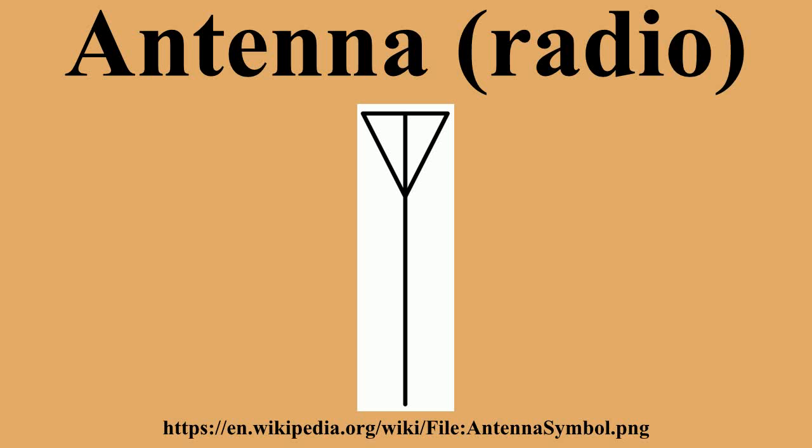Since monopole antennas rely on a conductive ground, a so-called grounding structure may be employed to provide a better ground contact to the Earth, which itself acts as a ground plane to perform that function regardless of an actual contact with the Earth. Antennas more complex than the dipole or vertical designs are usually intended to increase the directivity and consequently the gain of the antenna. This can be accomplished in many different ways, leading to a plethora of antenna designs. The vast majority of designs are fed with a balanced line and are based on the dipole antenna with additional components which increase its directionality.